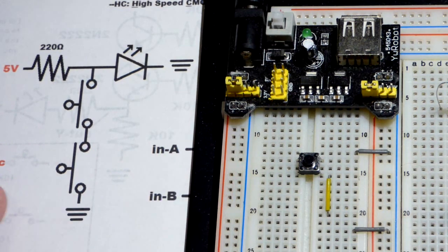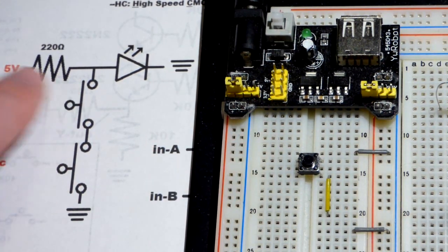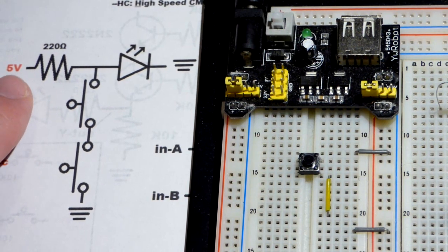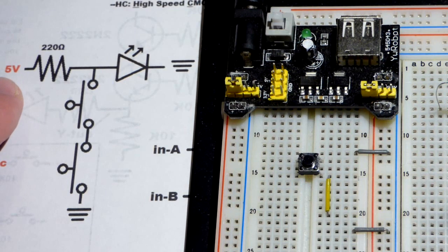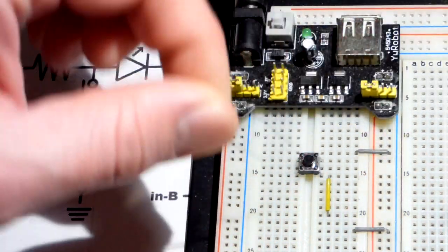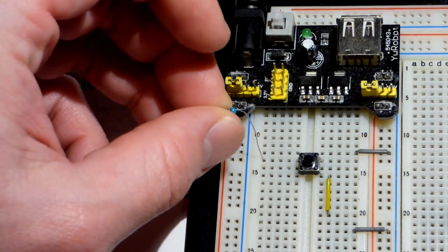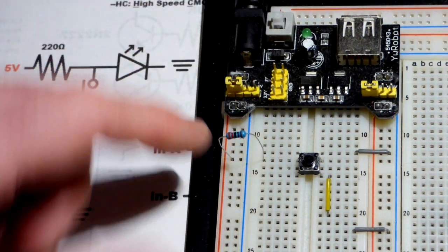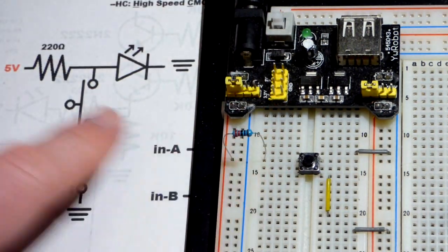So now we want to connect to the top of the switch a 220 ohm resistor that goes directly to the positive side of the power supply. So now digital electronics, the integrated circuits especially, probably will operate at 5 volts. With the switch, voltage doesn't really matter. Whatever the switch can handle. And then of course the rest of the components. But the integrated circuits are a lot more delicate. So we have the 220 ohm resistor.